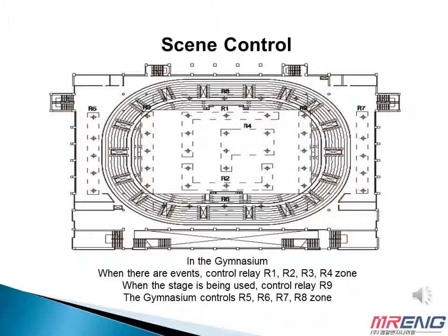In the gymnasium, the scene control function is the best option for lighting control. Unlike the office area, it is not controlled by certain time zones. It is operating intermittently for games and stage use. To apply the scene control function, configure the zones first, and then configure the circuit available for the scene control. Use the time function when there is an event. Select the scene button by switch at the specific zone area or central monitoring panel.